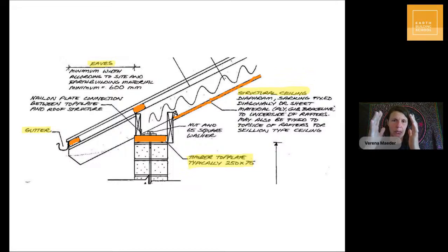And just having a roof up there that is not in itself braced is not enough. It can move quite a lot. So you have to introduce something in the roof that also stiffens the roof, that gives bracing to the actual roof structure. And then it is like putting the lid onto the box and everything is more stable, stiffer.